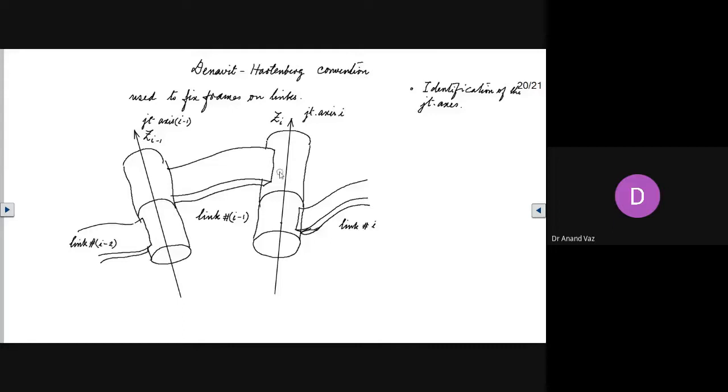So how do we specify this? That is expressed in terms of what we call the link parameters. So now let us figure out what the link parameters are. The first link parameter specifies the relative position of this axis with respect to this one in terms of distance. How far is this axis located with respect to this? For that, we draw a common perpendicular to these two axes. So the first thing is you have to draw a common perpendicular.